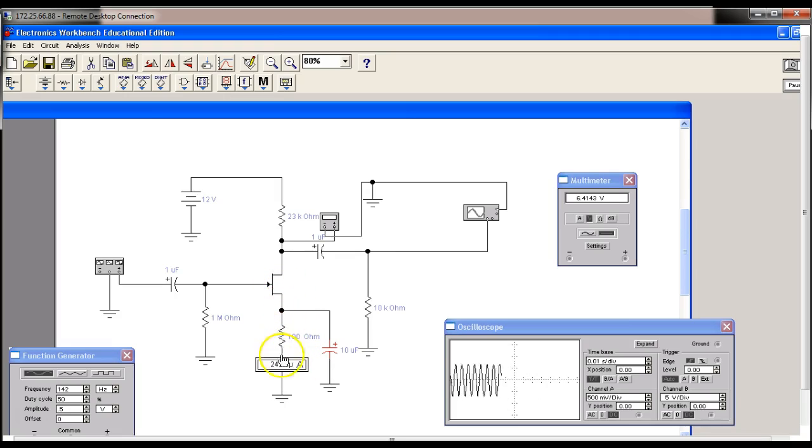When we have current flow through this, it drops a voltage, which makes this point right here positive. This guy's sitting at 0 volts and this guy is sitting at a positive voltage. So when we measure the voltage gate to source, this voltage right here turns out to be negative, which is really neat. The current flowing through here makes this positive, so this over here is negative with respect to this voltage, right?